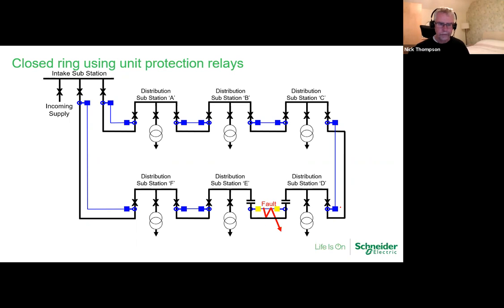Now then, in both examples I've just shown you, one of the key things to good network management is monitoring. You can put all the fancy stuff into the substation, you can have the best protection set up, but if you're not monitoring it, then if we get another fault up here, and we haven't monitored it, and we haven't done anything about our original fault around here, then the current will go to this point here, then that one will trip, or maybe that one will trip, and we could ultimately lose not just one substation.